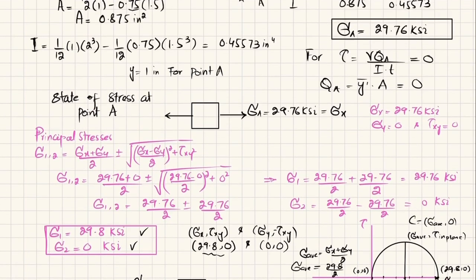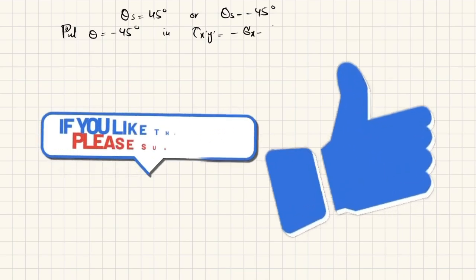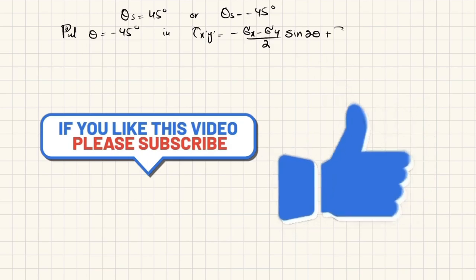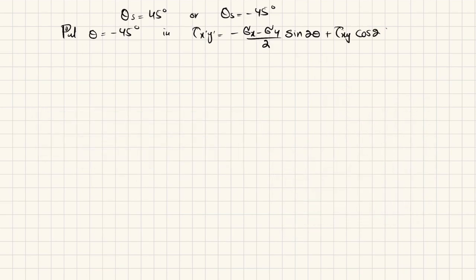Now we'll move to our next page. So we have theta s is equal to 45 and minus 45. So theta s is 45 degree or theta s is equal to minus 45 degree. So put theta equal to minus 45 degree in tau of x dash y dash, which is the transformed stress when the element is rotated through any angle. So sigma x minus sigma y divided by 2 into sine of 2 theta plus tau of xy cos of 2 theta.